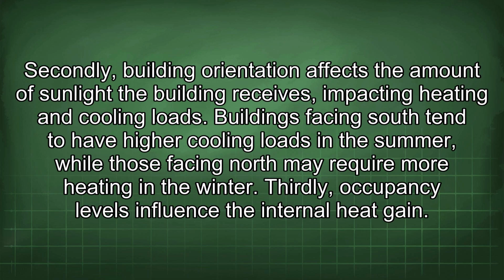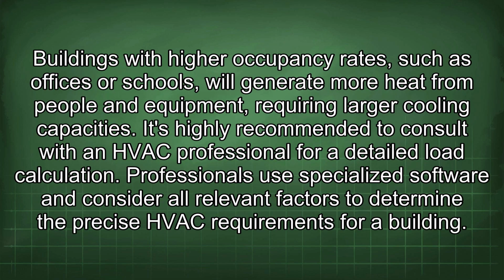Secondly, building orientation affects the amount of sunlight the building receives, impacting heating and cooling loads. Buildings facing south tend to have high cooling loads in the summer, while those facing north may require more heating in the winter. Thirdly, occupancy levels influence the internal heat gain. Buildings with higher occupancy rates, such as offices or schools, will generate more heat from people and equipment, requiring larger cooling capacities. It's highly recommended to consult with an HVAC professional for detailed load calculation.